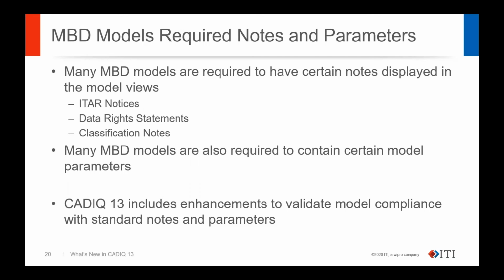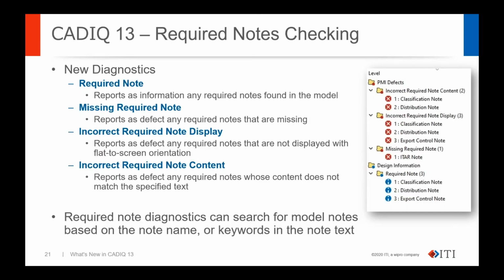And we've added a number of enhancements in CADIQ 13 to validate that models are complying with those required notes and parameters that need to be in there as a standard. So the first thing is around checking for required notes. We've added 4 new diagnostics here to look for these notes and report on when they're not meeting the requirements.